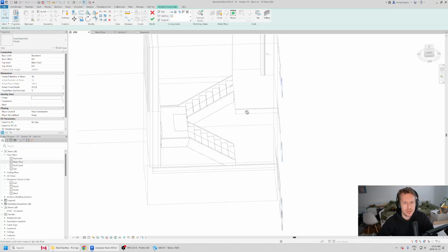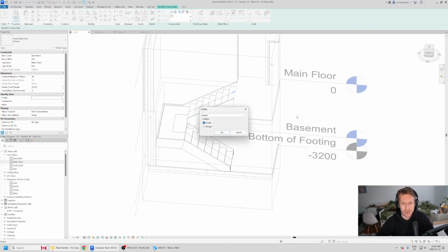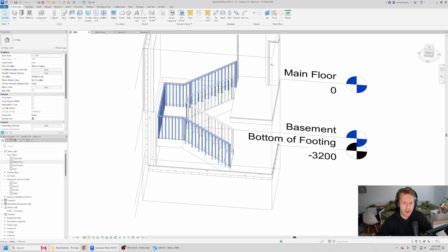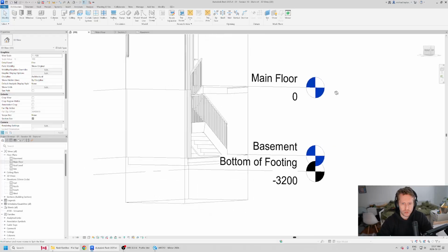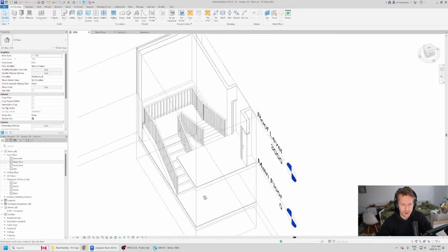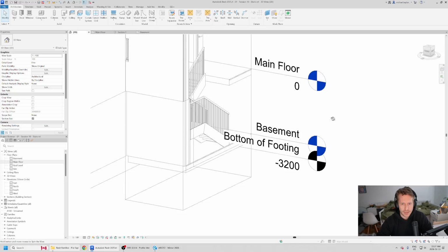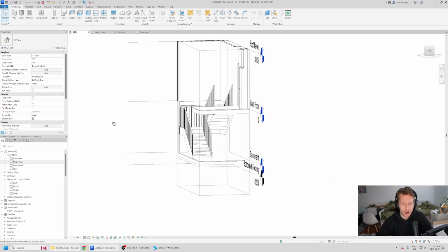And what we can do now is, if we hit the railing command, we can set it. We can choose which railing type we'd like, and we can change the position. So if I hit OK, we're just choosing it. It actually hasn't generated yet. I have to hit the check mark, and then it will complete the model. And look at that. So now we've got this wonderful little stair that's been generated for us. And one thing's missing, but we are in pretty good shape.